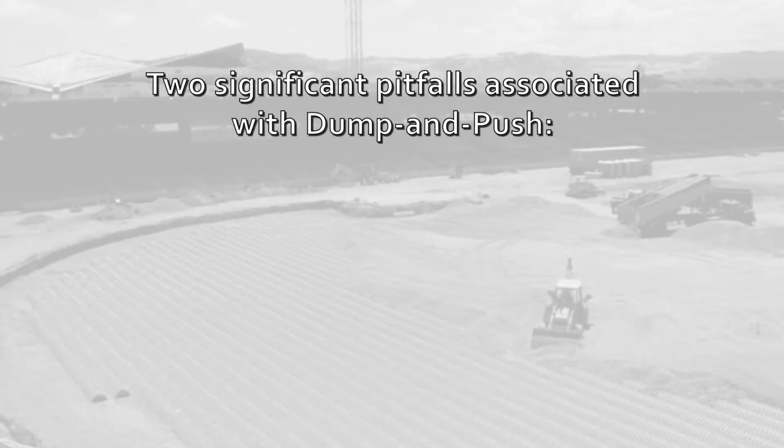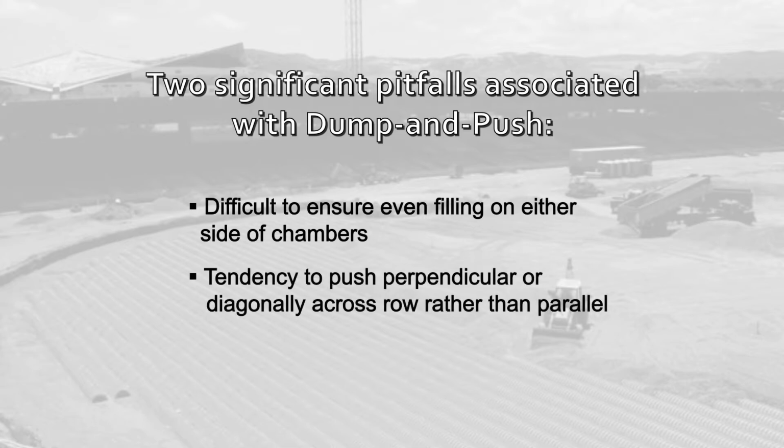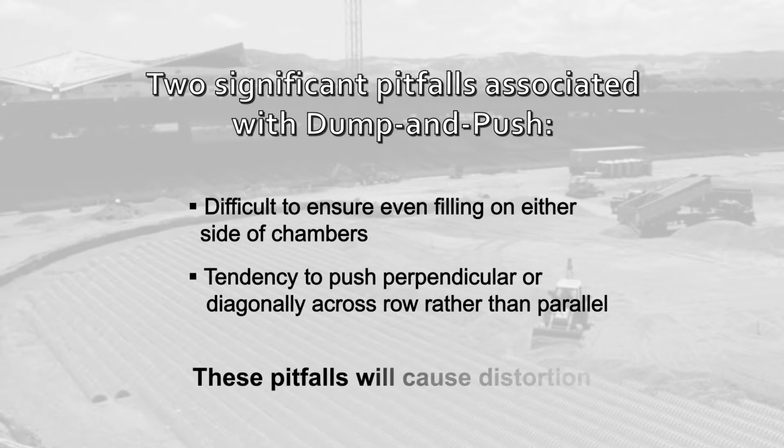Two significant pitfalls associated with dump and push are first, that it's very difficult to ensure even filling of embedment stone on either side of the dozer blade, causing chambers on either side of the dozer to distort. And secondly, that the tendency of the operator is to push perpendicular or diagonally across the rows as the backfilling proceeds along the bed, rather than always pushing parallel from the starting edge of the bed all the way to the leading edge of the fill. Pushing perpendicular to the chamber rows with insufficient cover will cause distortion of chambers. Therefore, the dump and push method is not an acceptable method to backfill chambers.